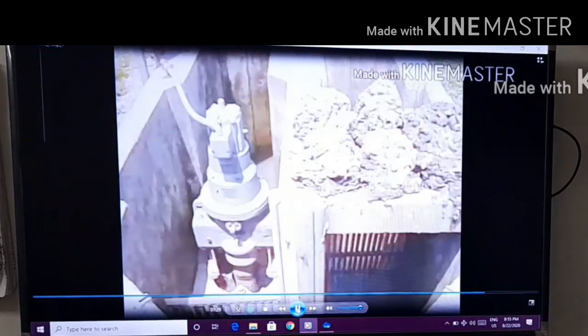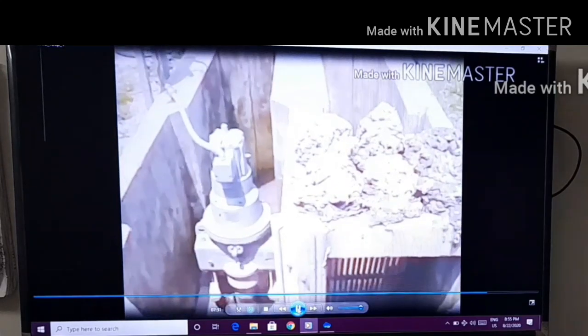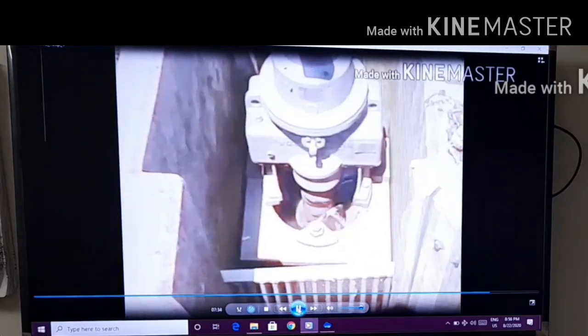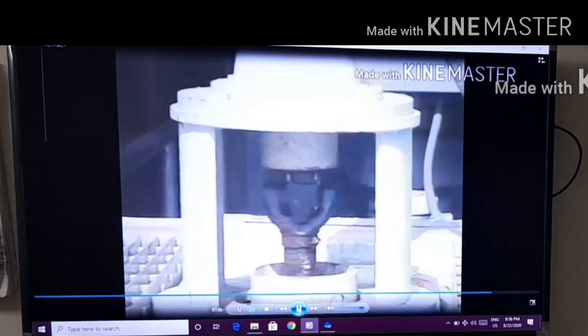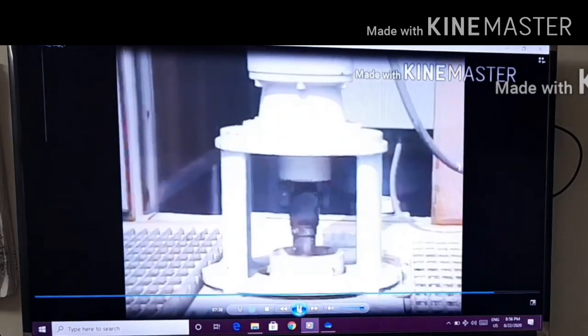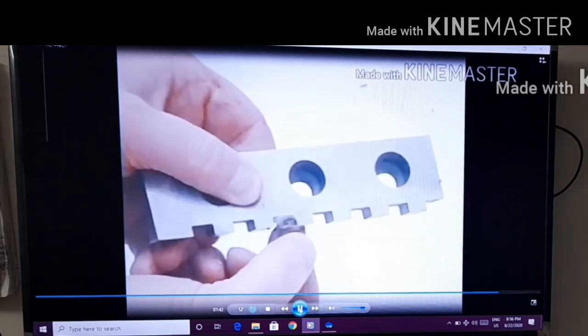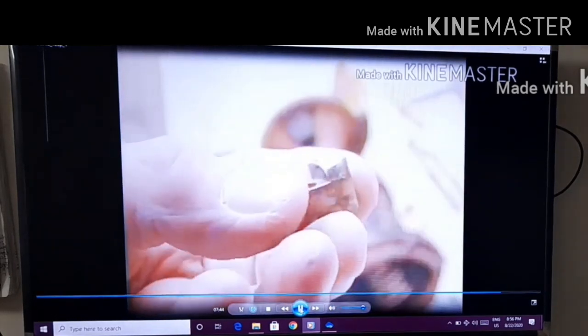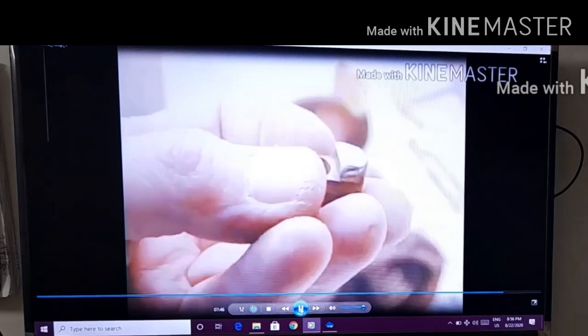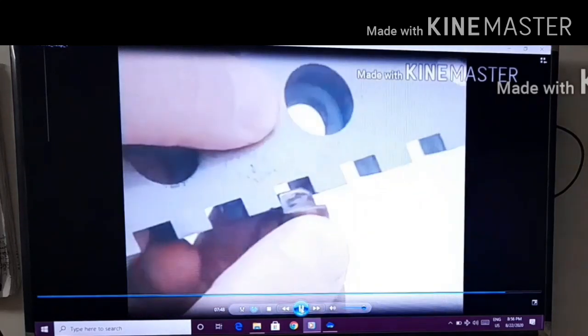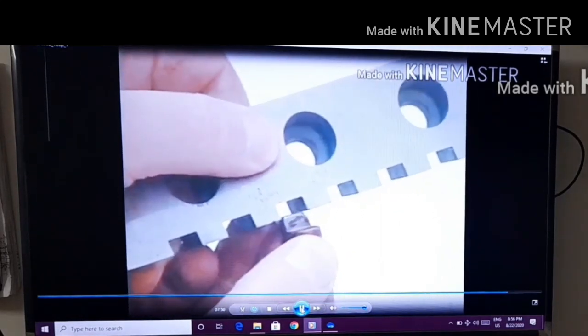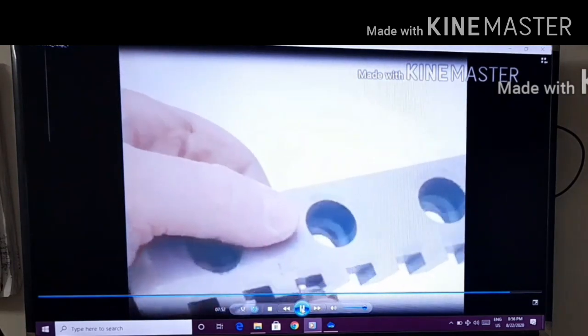The comminutor generally has a set of both rotating and stationary cutting heads. Some comminutors oscillate back and forth, while others turn in a complete circle. In either case, it is necessary to keep the comminutor equipped with sharp cutter heads to ensure proper operation. When cutter heads become dull, the comminutor tends to tear the material instead of shearing it as it is designed to do. Generally, it is not effective to sharpen comminutor teeth, as sharpening only compounds the problem.